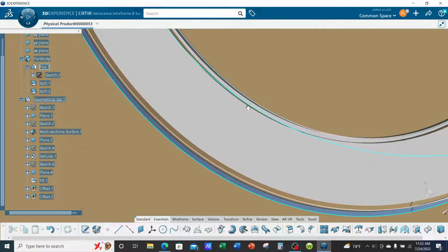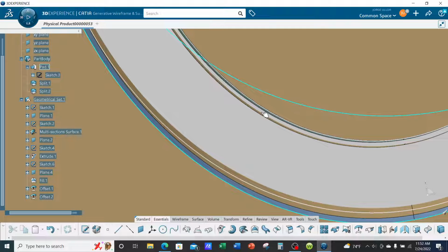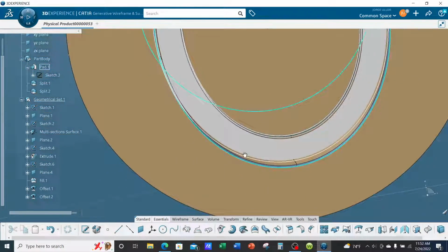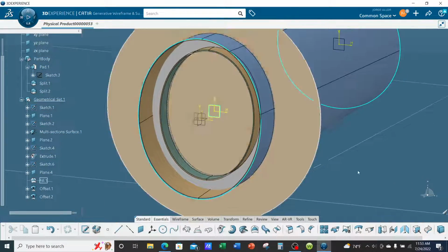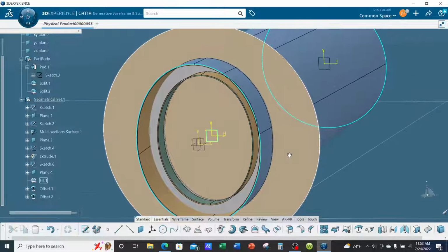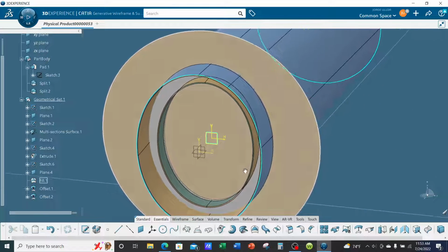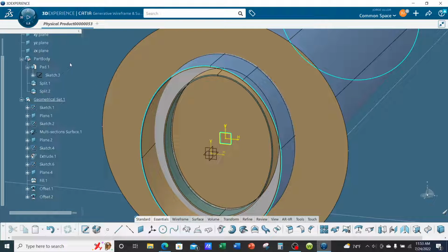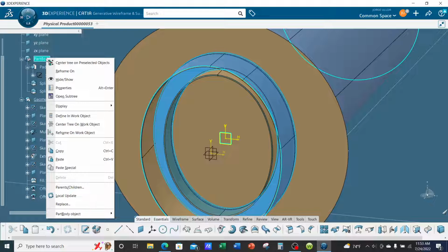So we can zoom in. Okay, so we'll have a flange on the inside and a flange on the outside. And this web will be 1/2 inch thick, just like the flanges. Okay, so now we need to combine the surfaces that we just created, the brown surfaces. Before I do that, I'm going to hide the solid. Right click, hide, so I don't click on the wrong thing.